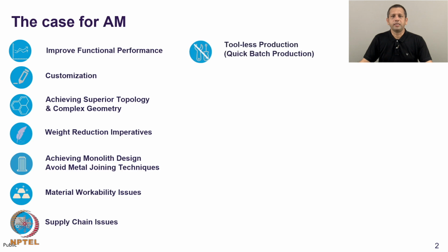As we now know already, additive manufacturing is based on CAD files or design. We do not need dies, tools and other large structures, for example, foundries and mills. This is a toolless production process, and thus we can make small batches or large batches of the parts that we need. Because of this new methodology of design, we can make faster design and we can make small changes iteratively in the part that we want to make more quickly.